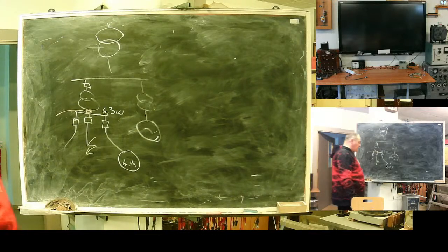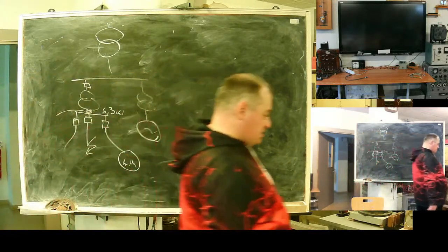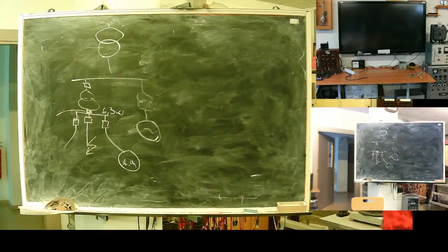But another one, since most faults are not symmetrical, even three-phase fault. How can a three-phase fault be created? Your personnel leave an earthing knife and put the line under voltage. It's a personal error.